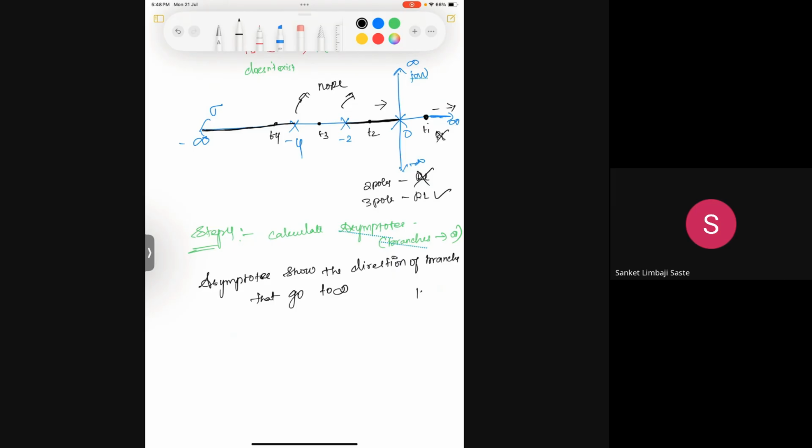When k equals 0, the root locus starts at the open loop poles, and when k equals infinity, it ends at the open loop zeros. For some systems, the poles can be here and the zeros can be here, so you don't know whether the root locus comes like this or this or this. The angle at which the root locus propagates from open loop poles to open loop zeros is determined using the asymptotes. This angle we are going to calculate in this step.